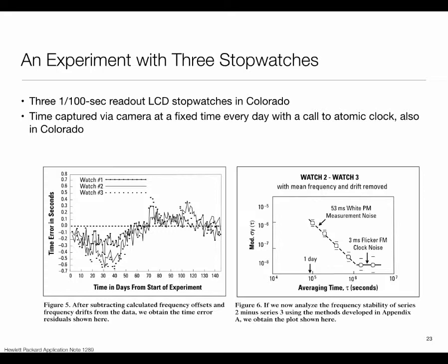So I talked about that odd number of inverters, that's like 500 ppm, 1000 ppm. Standard crystal oscillators, 40 to 50 ppm, maybe 20 ppm. TCXOs, 1 ppm, maybe 0.1 ppm.